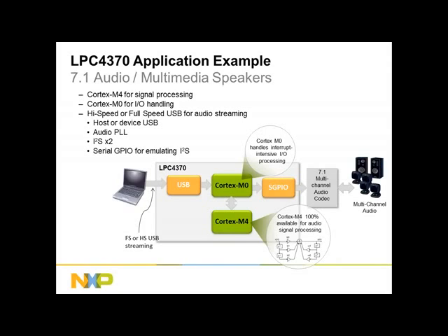You also get some SIMD instructions, which the compiler doesn't really take advantage of, but you see those in optimized libraries typically. And you also get a floating point unit, so making this the M4F, if you will. If you don't need any of those things, the M3 is as good as the M4. There's no extra horsepower benefit, etc., if it's running at the same speed. If you do need those things, it's certainly nicer to have the M4.